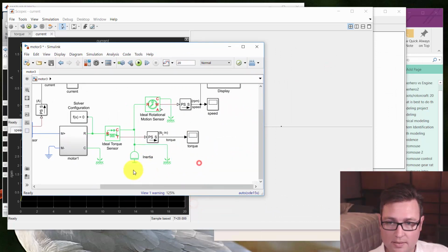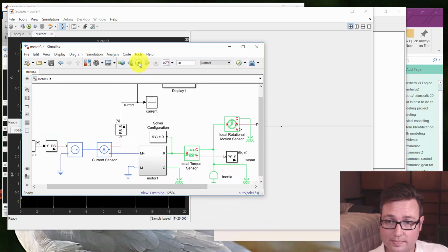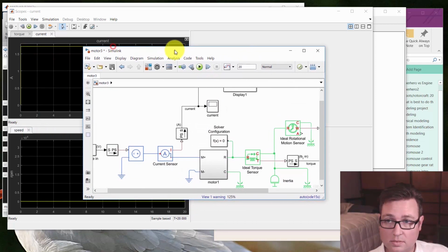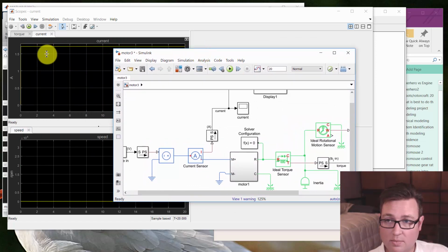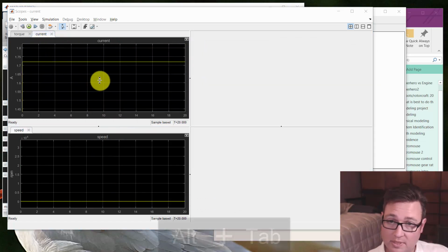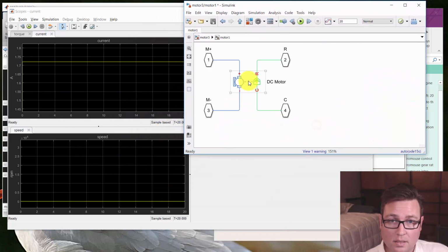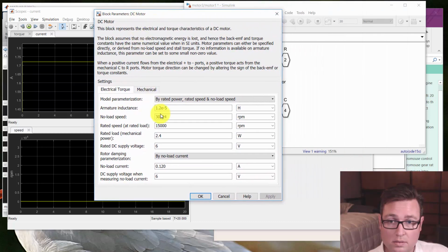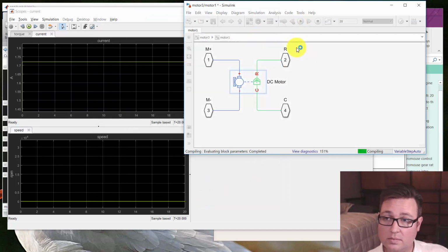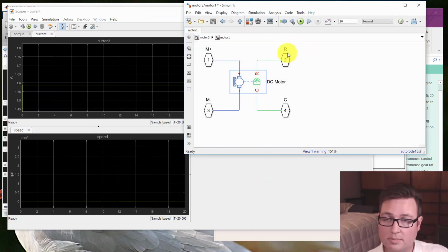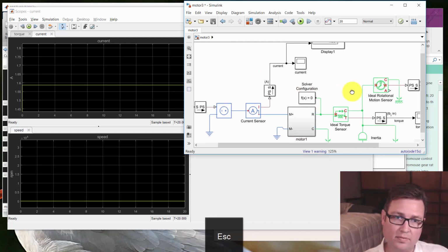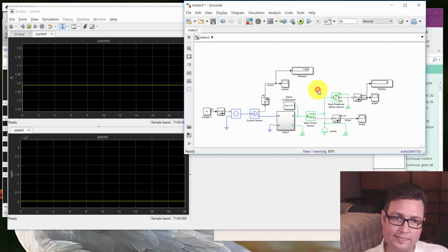So we'll turn this back on to lock ourselves into a stall and hit go. Remember, we want to get this at 1.6. We're about 1.7 something now. So 2.2 watts and go. That's pretty close. I'm going to say that's good enough. We're pretty close to 1.6 amps. Okay, so now we have a motor that's good enough.